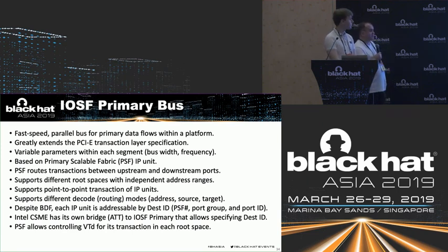It replaces PCI Express for on-die communications and greatly extends its transaction layer specification. The heart of the IOSF primary bus is a hardware unit named Primary Scalable Fabric, or PSF.